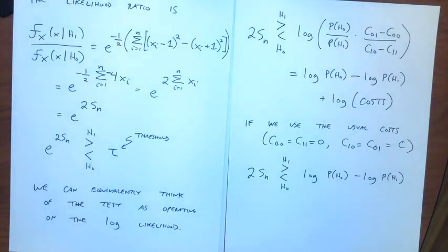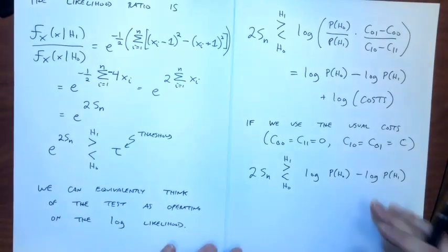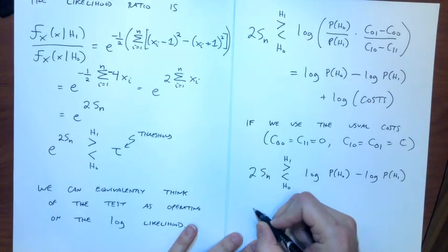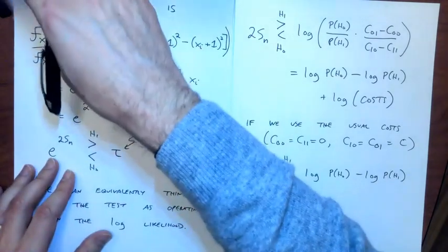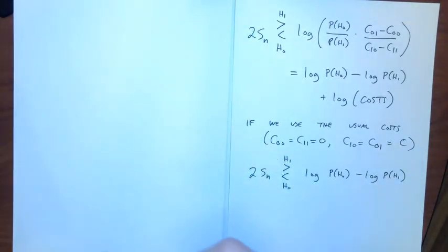And then I could say, well, okay, if the hypotheses initially are equally probable, right? So if I know that I'm putting an equal amount of +1s and -1s through the channel, then this just becomes 0 on this side, and that's the same thing as the maximum likelihood test, actually.